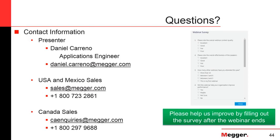And also in modern equipment, once you measure that float current, you actually do that at the very beginning of the test. The instrument will take that into account automatically. But again, it's good that you doing the testing know that you have to measure that float current to take it into account when doing the resistance calculations.